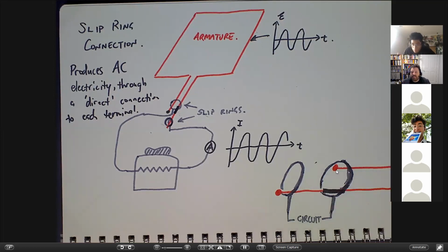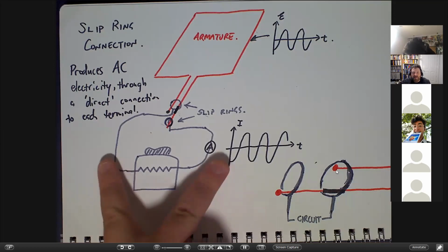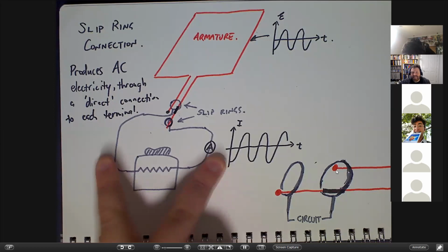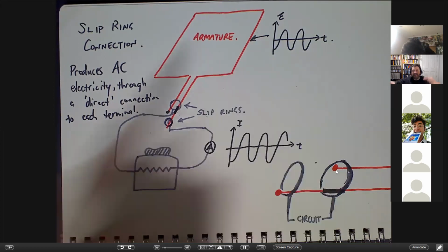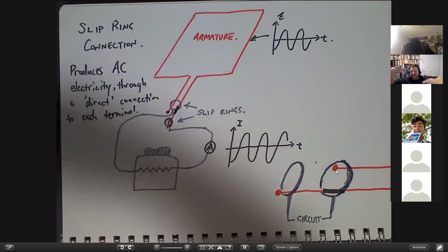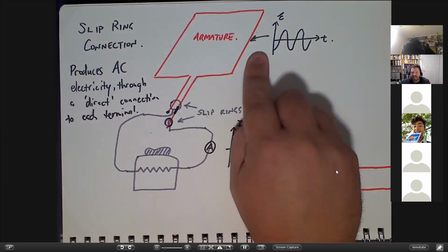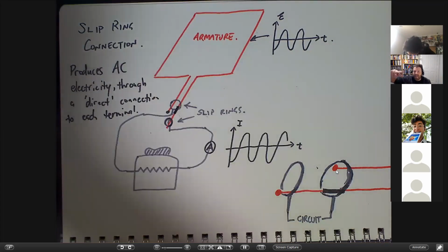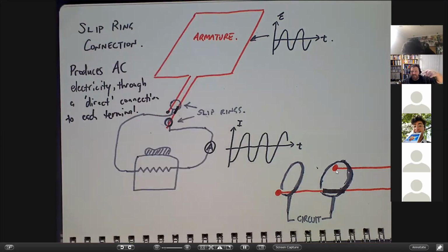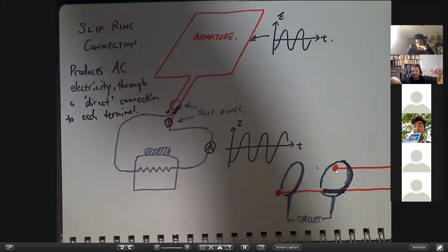Now, in answer to Ricky's questions from before, if we put magnets around this loop here and got it spinning at the same rate that this was spinning here, you could have them going together. So this current here, this generating over here, so we'd be winding our handle over here, that would be spinning this, creating electricity, that electricity would go into this one, and then that would become a motor. So you could have a generator driving a motor.